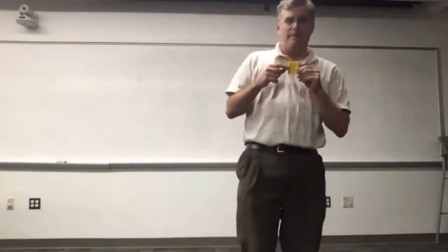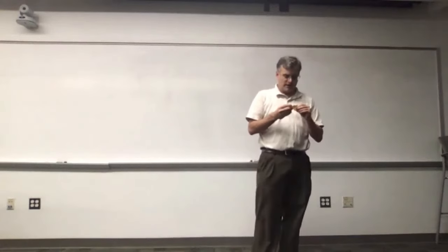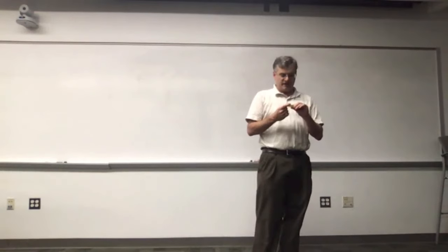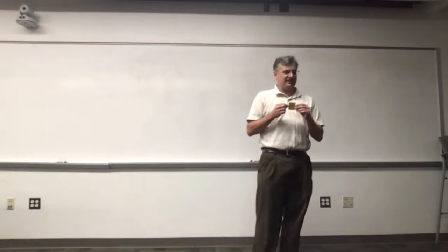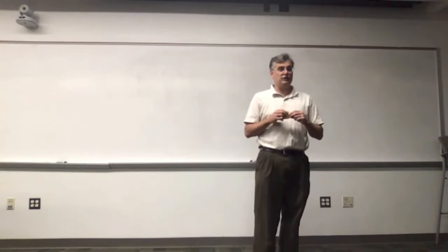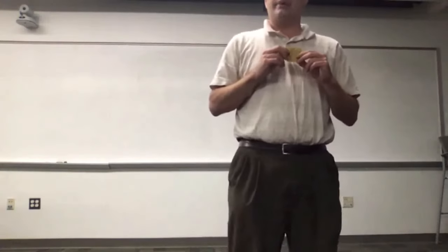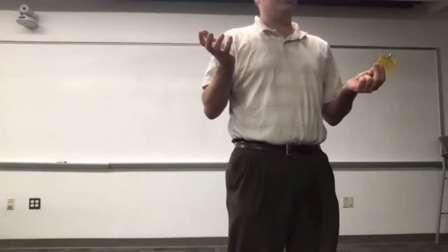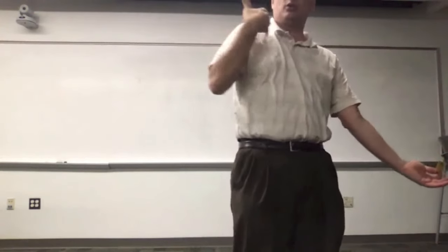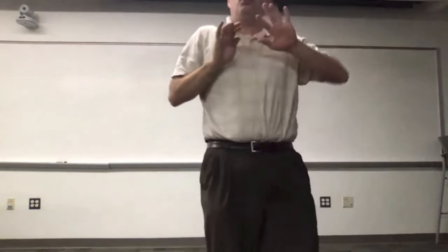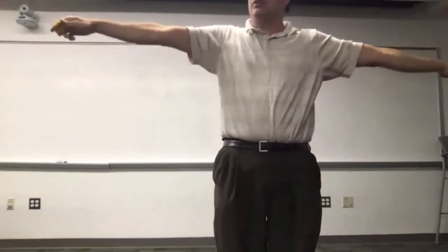Before we do the math and start mathing all over the board, I brought in an example of an unorthodox Yagi antenna. It's based on the exact same principle, except instead of using a half-wave dipole as the driving element, it uses a V dipole. We talked about the V dipole in this class. It's just a dipole, but you bend it over a little bit, and it makes a little traveling wave. It actually pushes the directivity of a dipole in one direction instead of keeping it omnidirectional.